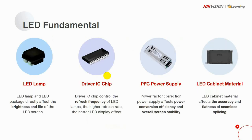Moreover, different parts play their own roles in LED screen. The lamp affects the brightness, and if it's defective, we have to repair it. Driver IC chip controls the refresh frequency of LED lamps. The higher the frequency, the better the display effect. Okay? And the PFC power affects power conversion efficiency and overall screen stability. With the help of the cabinet, we pass the lamp board with magnet on it. It can help us to have seamless splicing.